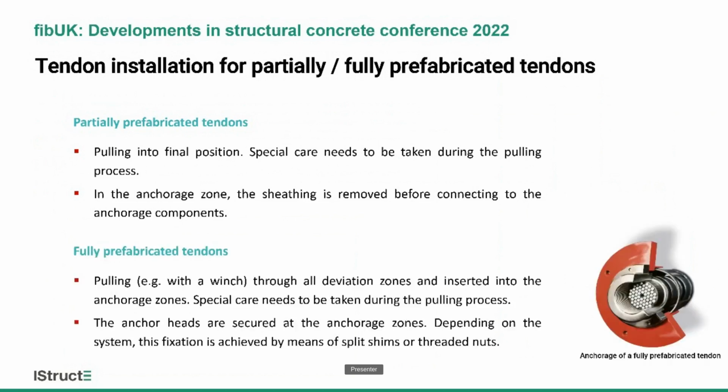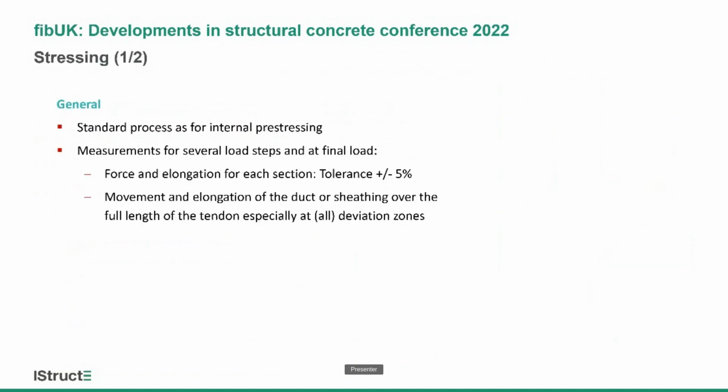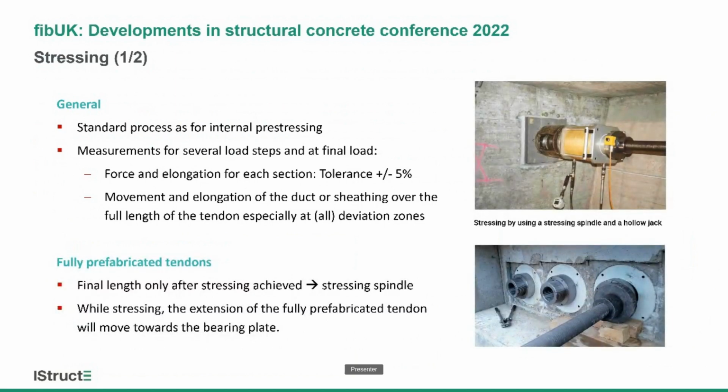For fully prefabricated, it's quite easy. It's just pulling the fully prefabricated tendon in, securing the anchor heads, and you are almost ready to start the stressing.